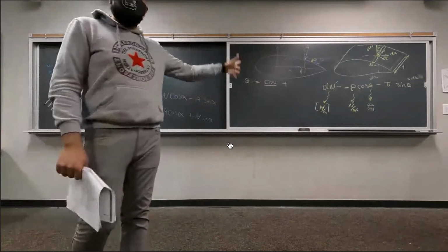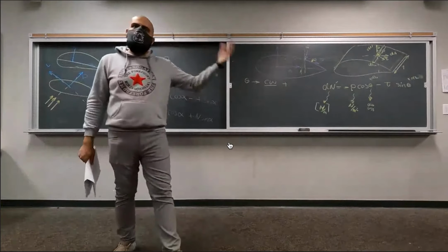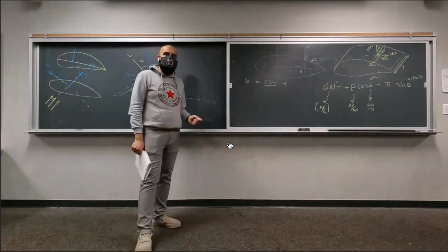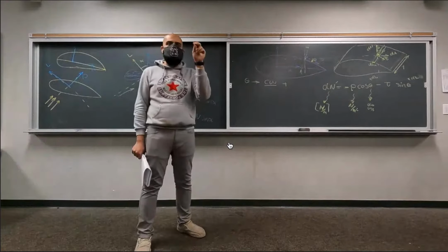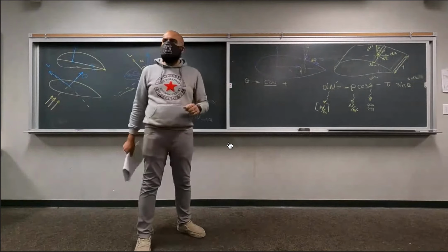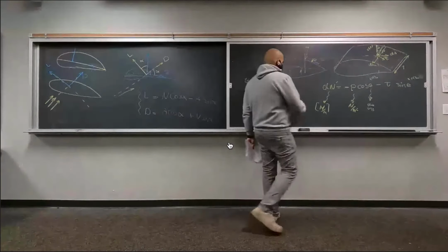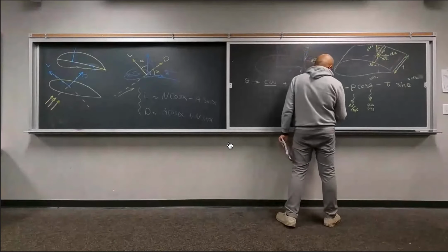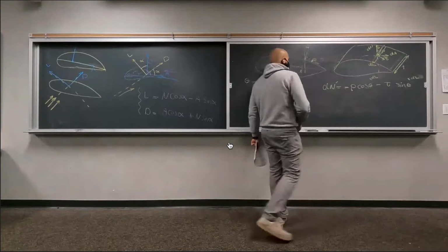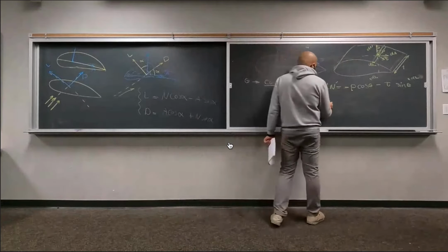If you're using lift, L prime refers to lift per unit length, right? D prime is going to refer to drag per unit length, right? If it was double prime, it means that it is a point force. It is essentially a pressure, right? It's going to be force per unit area. Does that make sense? Okay. So since at this point we are dealing with 2-dimensional cases, we are going to stick to N prime. So let's do dA prime.